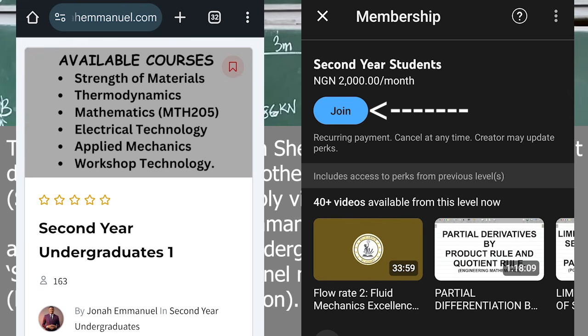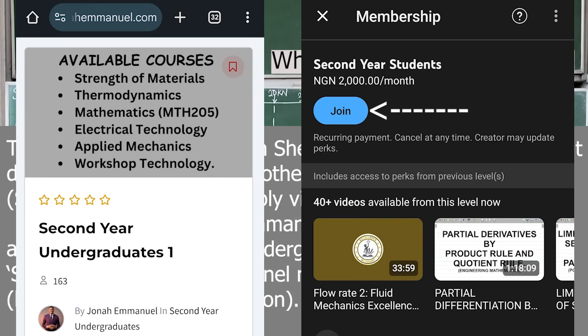After this, we are not still done. We still have to do two calculations. Number one, the position of the maximum bending moment. Number two, the point of contraflexion. After shear force and bending moment diagrams, you are asked to find something called the critical points. There are two critical points. Number one is the position of maximum bending moment. Number two is the point of contraflexion. Hang on, we'll deal with this in our next example.